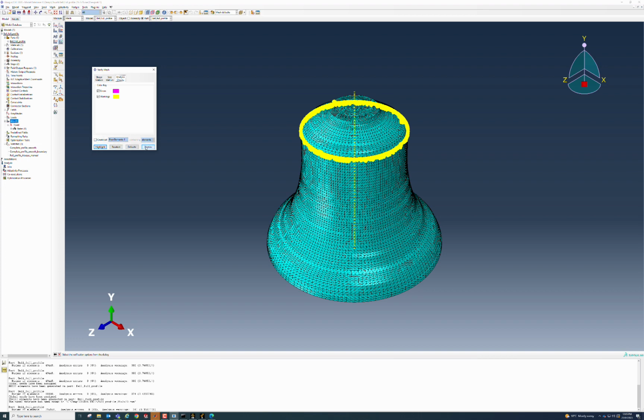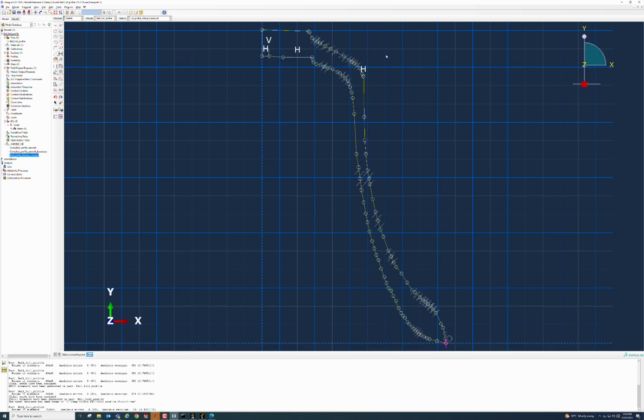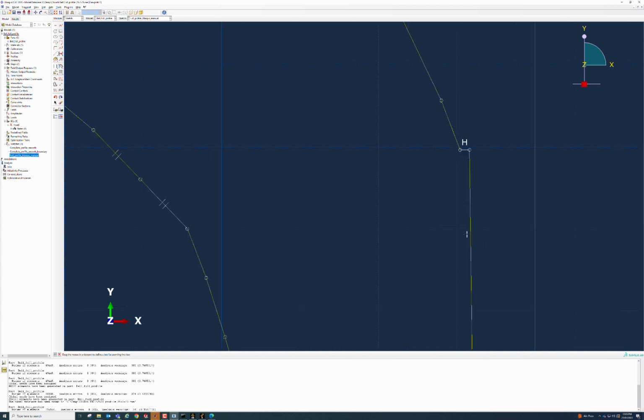We can define for ourselves what we consider to be a high aspect ratio element. So we're essentially in control. Warnings are acceptable, errors will give us problems during meshing. If we have another look, as I was explaining previously, at the root cause of the issues that we're observing, we can see that there are indeed some step regions here with these two data points.